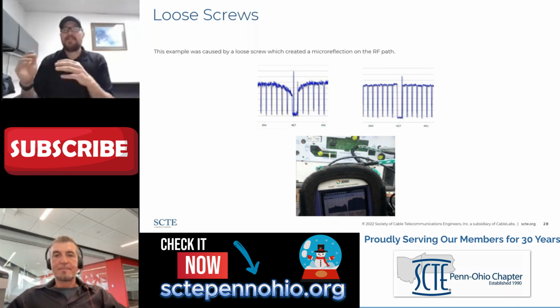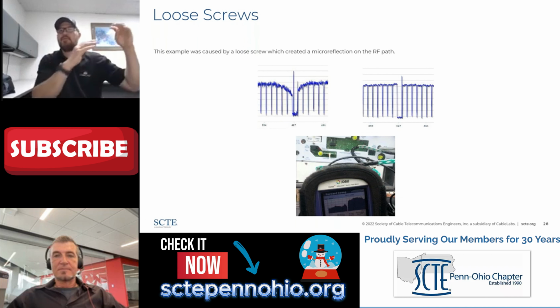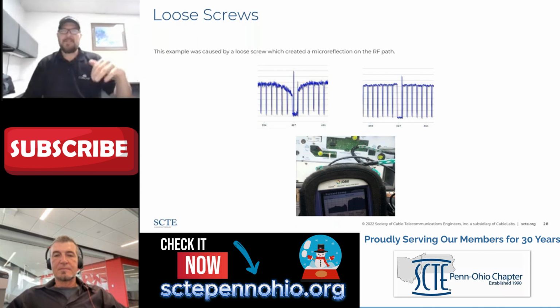So to take that extension a little further, if the ALCs are trying to correct for a pilot that is part of a suckout, it's going to amplify all of the output of the entire spectrum, not just that narrow portion.